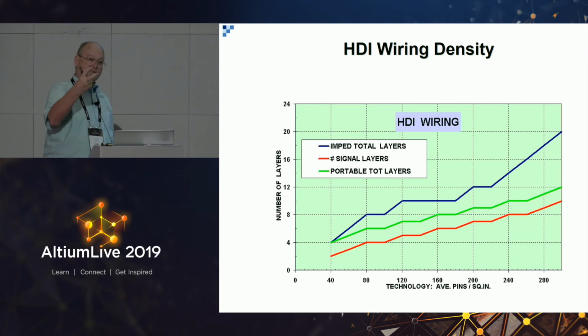And like I said, if you put the silicon directly on the board, then that's the package you have to design for. But you notice here, the number of signal layers are 4, 8, and 12. It's not 24, 30, 36. And that's simply because HDI offers the opportunity for 3 to 4 to 5 times higher density with the same number of signal layers.